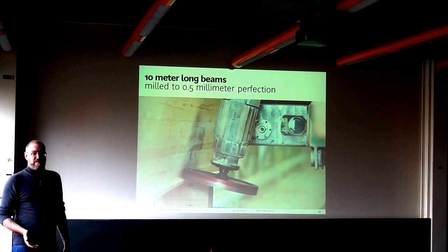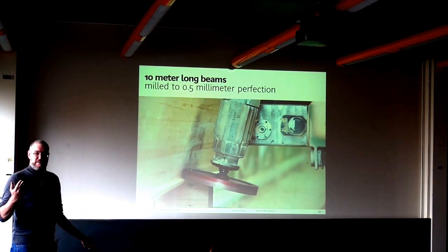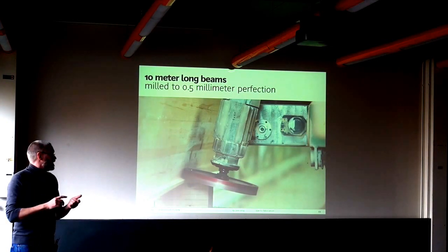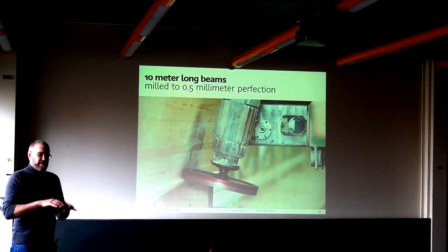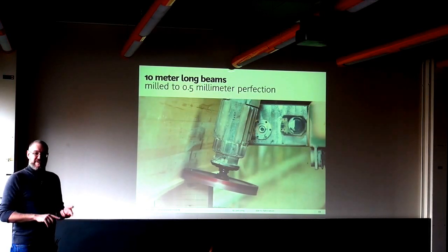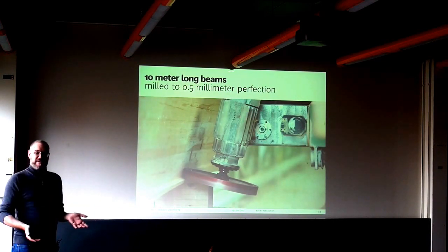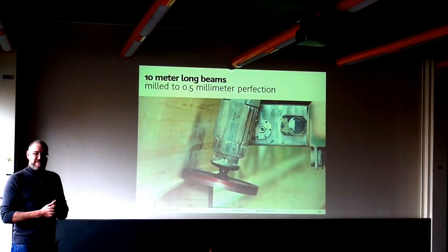Of course, you have the same tolerance problems that you have everywhere. I mean, timber is reacting to moisture, steel is reacting to temperature more than timber, and vice versa. So you always have to care about environmental conditions during fabrication, assembly, and later on also. All building materials are moving somehow, expanding, shrinking, bending, being elastic or whatever.